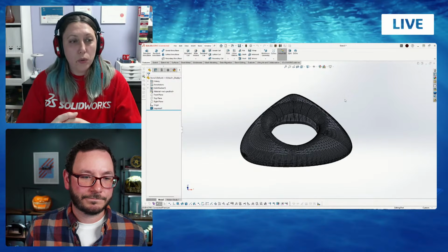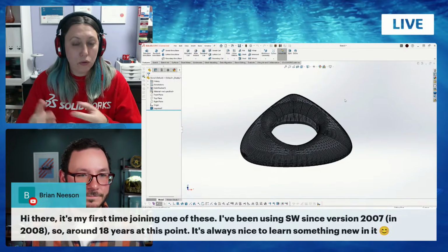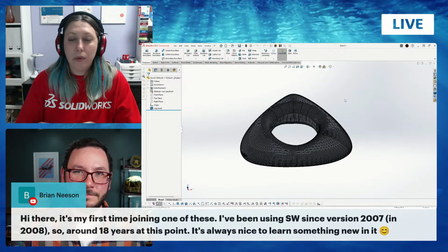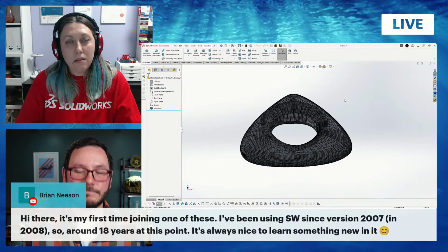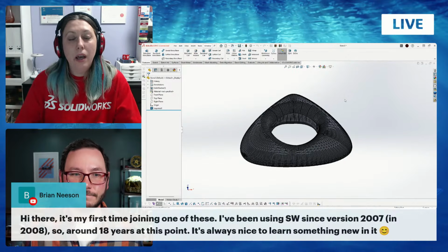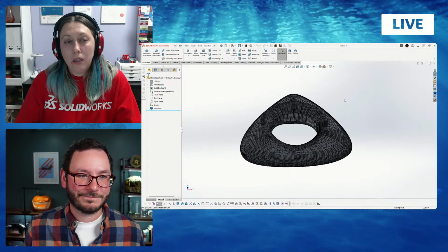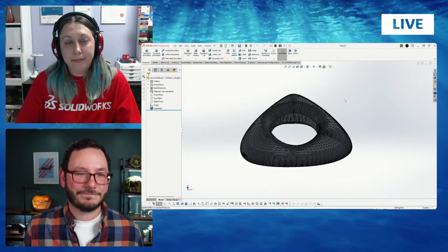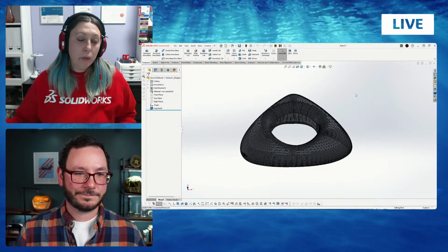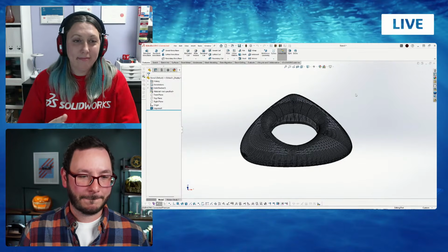Standard import is suitable if you need it from time to time, or if you need just a graphic object to visualize something in your model, like a very simple example, you're making interior design. It's hard to find step files of plants, for example, but it's easy to find STLs. And you want to put this plant as decoration, you don't have to convert it. You can keep it as a graphic body. Yep, that's a great point. Gives you a lot more flexibility. And it will be much lighter than if you have a lot of steps inside.